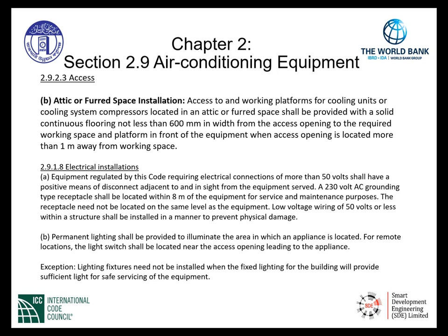A 230 volt AC grounding type receptacle shall be located within 8 meters of the equipment for service and maintenance purposes. The receptacle need not be located on the same level as the equipment, and low voltage wiring of 50 volts or less within the structure shall be installed in a manner to prevent physical damage. The low voltage wiring of 50 volts or less may be the thermostat wire, control wiring for the air conditioning